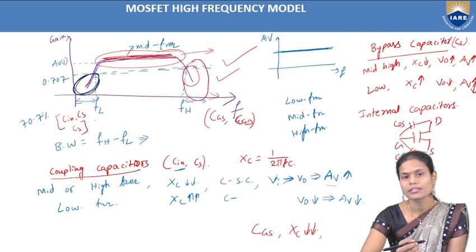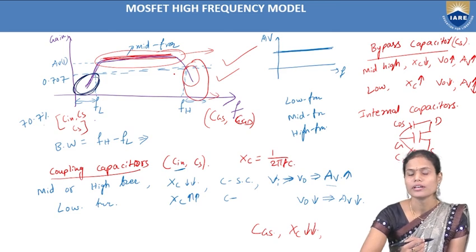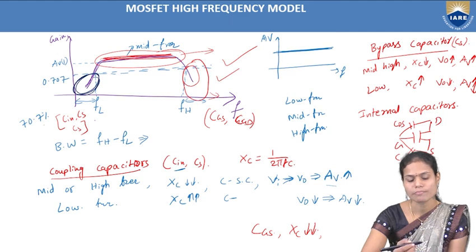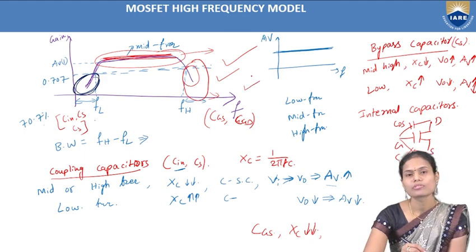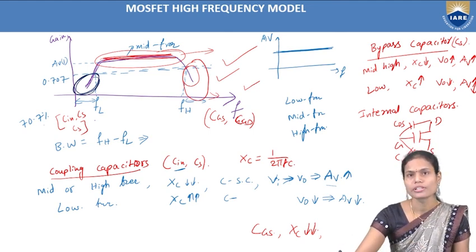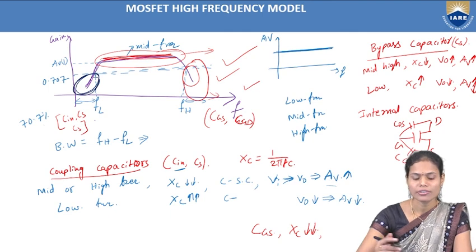Similarly, if we take transformer coupled amplifiers, because of the windings of the transformer, there is a change in the frequency response. If the windings change, the resistance values in the circuit change, so the frequency response will also change here. So in this way, because of the different capacitors' action, the frequency response of the circuit will change, especially at high frequency range.